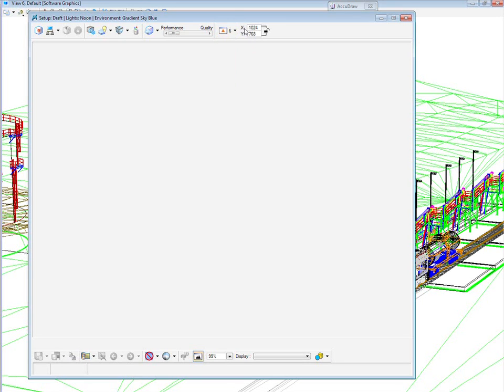It's the active view. Okay, and really important too, your XY size. I've got it as a 1024 by 768. If you were to click on the lock here, it will actually reduce it down or bang it up to other values. But if you want a specific value, you can come in here, 768.